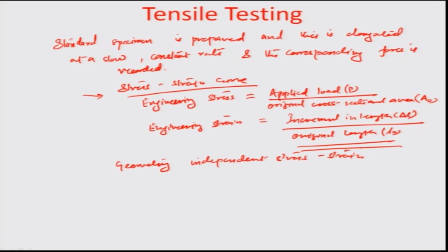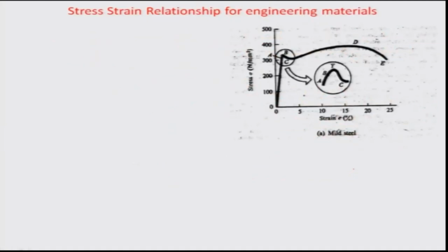So, the stress strain relationship in case of mild steel has been very well recorded and well used and known. Basically this is how the plots are being made with the strain or percentage elongation as I defined earlier on the x axis and the stress in Newton per millimeter square on the y axis. You can see here that the stress strain relationship is linear up to a point A. If you look at this particular section of the curve, it is a linear increase.